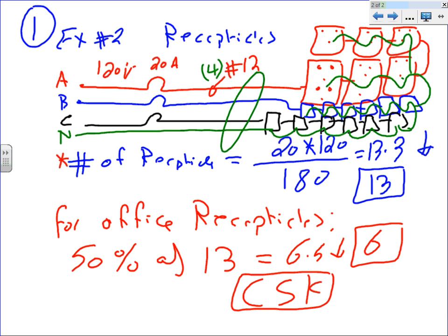So don't take it like, if it's 8 receptacles, guys, and I have to pull another circuit for only 2 receptacles, what would I do? I just put the 8 receptacles in. But I start worried if I have 10 receptacles or more. If you hit 10, split them, 5, 5. But if you have 8, close to 8, 9, you hit 10, just split them. Okay? But the rule of thumb is 6 or more on one circuit.